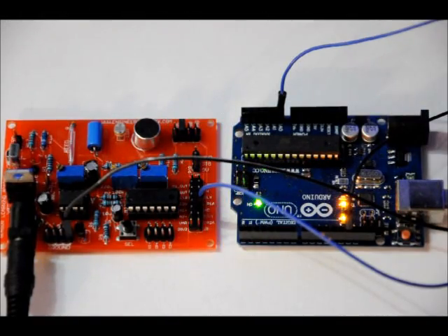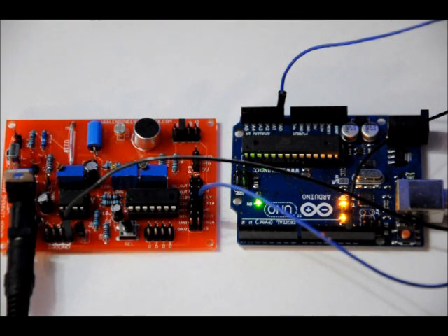All that I've done here is connected the div1 line to the A0 pin on my Arduino and connected ground from the power supply pin block to ground on the Arduino. I've powered both boards, and I've used the analog read serial code. It's a basic code that's included with your Arduino under examples. Basic analog read serial, and you open that up, you load your Arduino board, and you open the serial monitor, and you can actually see a number that's been taken from the ADC, and it prints it on the screen continuously.